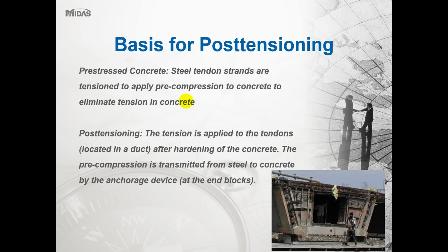Post-tensioning, where pre-stress is applied after casting of the concrete, is commonly used for voided decks and box girders, and can cater to long spans, basically spans of more than 30 meters, and in situ concrete construction, and things like that. So we do this with the construction stage.